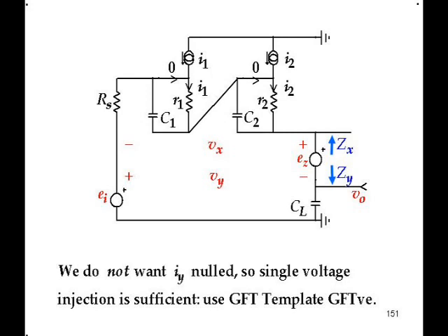What impedance do you see looking back at infinite frequency? The two caps are short. And Ei is 0 for the impedance Zx. So you see Rs. So you know that the Zx is flat at 0 frequency and it's flat at infinite frequency, and therefore because it has two poles it must have two zeros as well.